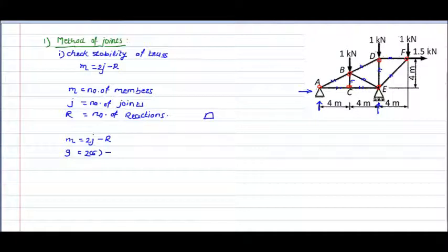Either way, here you can just write it down: for a hinge support, always show 2 reactions, and for a roller support there should be only 1 reaction. So now the total number of reactions is 1, 2 and 3.